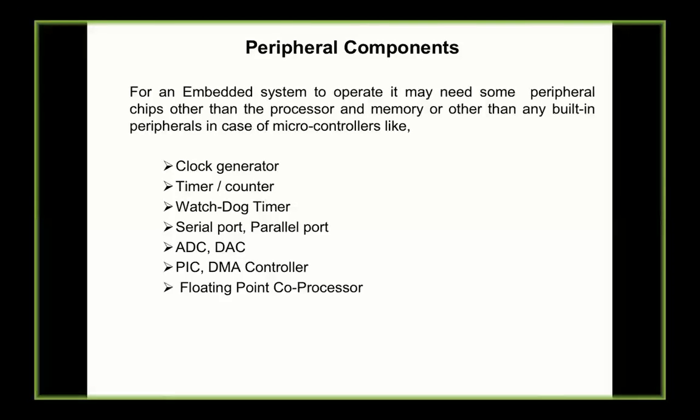Or if you have QNX and SMX, there is watchdog_create, and then you pass parameters, initialize them, and then attach an application alarm with it. It has a callback function which you can call, which can log something, or it can be connected to some kind of a PWM, pulse width modulator. It can beep and panic you, hey, come on, something is going wrong in your system, it's time to look at your health.